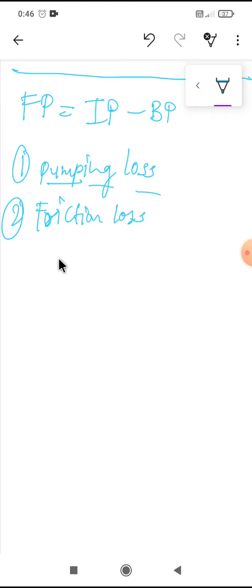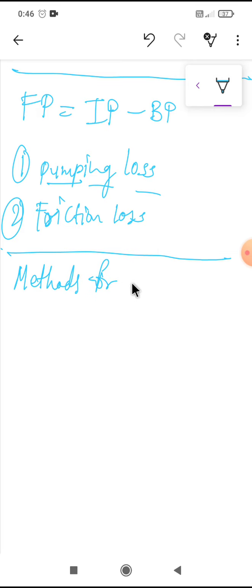So it should be the aim of the designer to have minimum loss of power in friction, and the friction power is used for the evaluation of indicated power and mechanical efficiency. Following this we will discuss methods used to find the friction power to estimate the performance of the engine. There are a total of four methods.